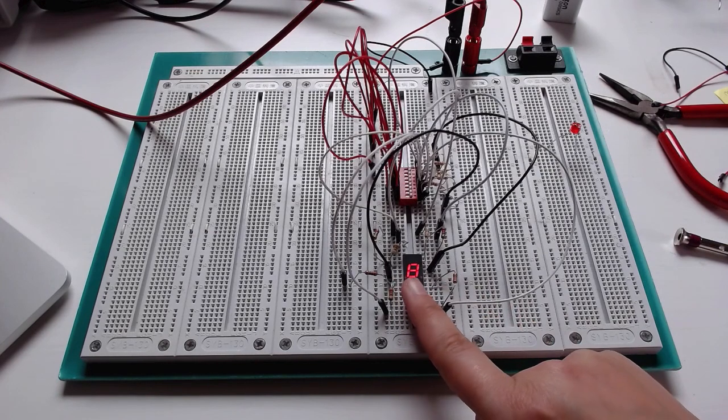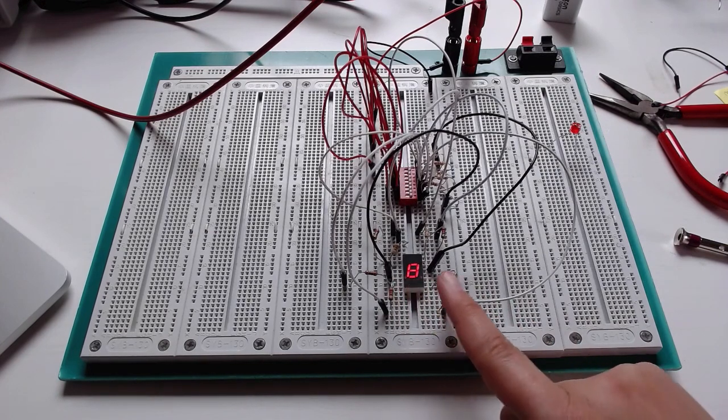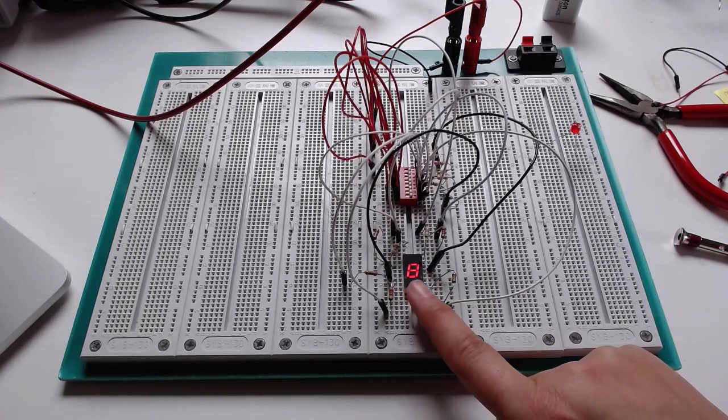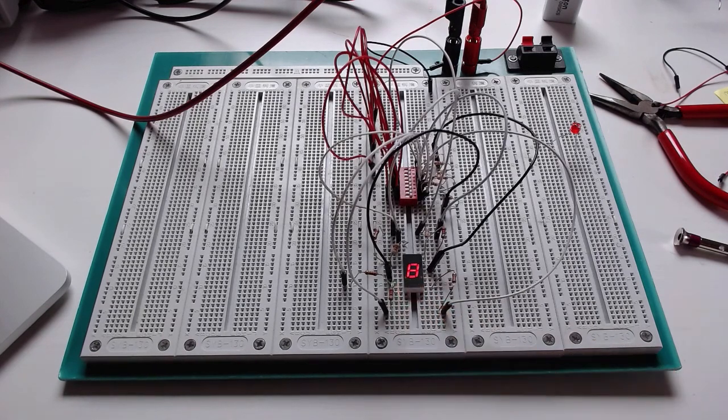Just as before, as long as we have the minimum resistor value met, which we've calculated for this specific display to be 75 ohms, it doesn't matter what value I use. For this display, 220 ohms, which is what I've used here, makes a pretty good readout that isn't too bright. I could use any value that gives a brightness that's good for my eyes to look at without having them hurt. But below 75 ohms, and I would worry that this would eventually burn out. Okay, so it's not an option not to use a current limiting resistor.